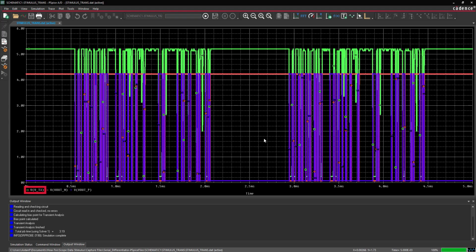The oscilloscope design is shown as the input trace, and a differential signal is generated by the chip in the design. Quickly and easily create a stimulus from oscilloscope data to create a realistic source and SPICE simulation with PSpice.